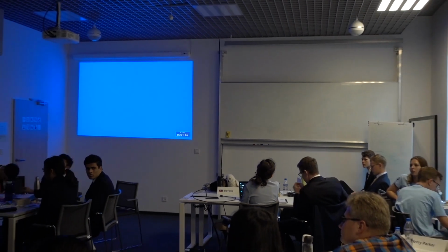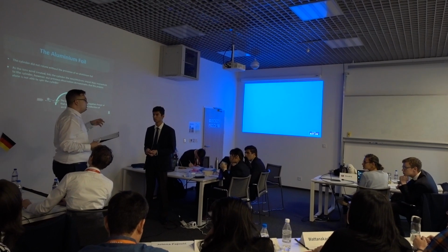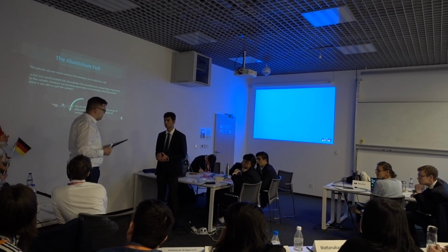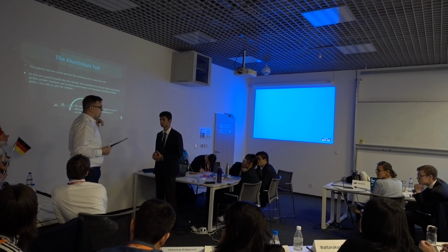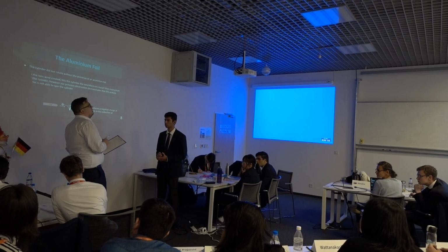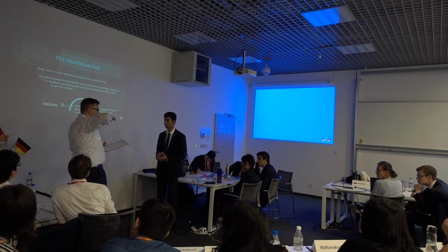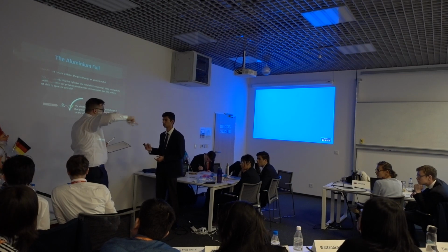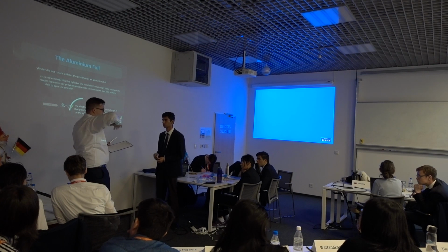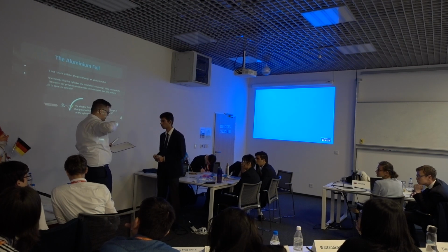Well, when you have a capacitor, you could calculate the energy it has from what charge it has at what voltage, and from that you could say that this charge is stuck on the rotor, and it is pulled to the different electrodes, and by what force, and you would proportionally get to the torque it creates. Do you agree? Yeah. Okay.